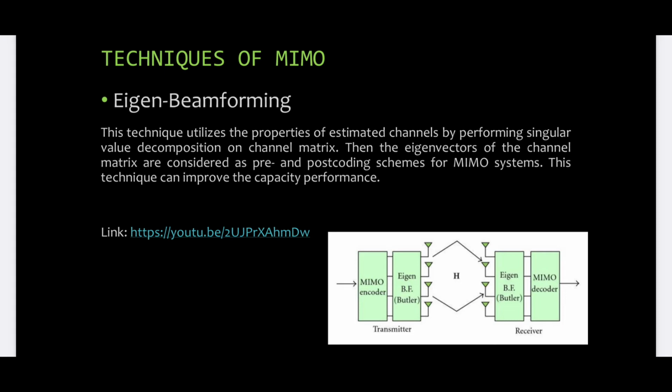which cause significant degradation. MIMO eigen beamforming, on the other hand, converts the signals from all the antennas into the digital domain, where sophisticated digital signal processing or DSP can be used. Eigen beamforming can thus, in effect, be done independently for each of the narrowband subcarriers of an orthogonal frequency division multiplexing or OFDM system. In particular, MIMO systems can utilize a type of beamforming known as eigen beamforming.